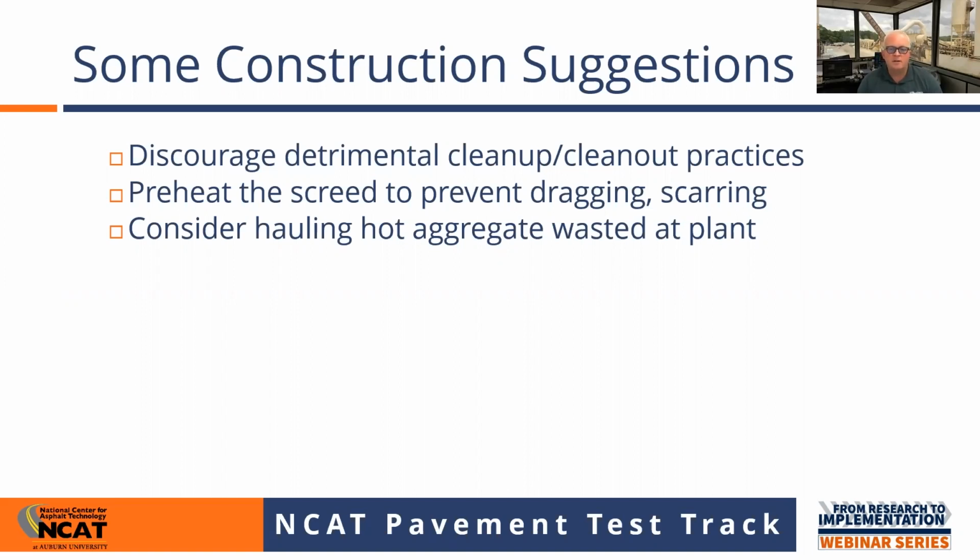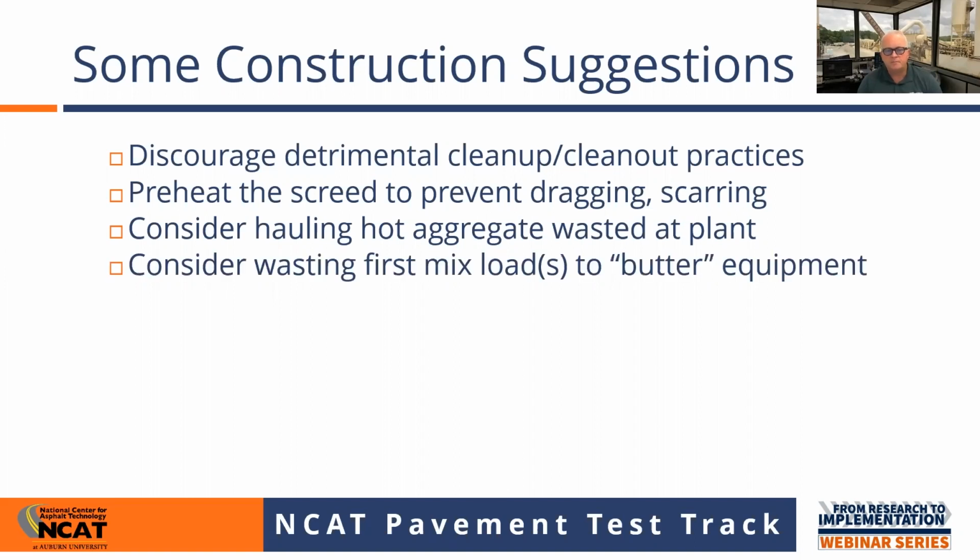And so if you consider hauling hot aggregate that you're wasting at the plant, or using that maybe to preheat your trucks, or maybe even preheat your transfer device, and just discharging that material, that uncoated material, off on the shoulder. But you can also consider wasting your first load of mix at the job site, and you got to be prepared for that. You got to have a specification in place for that, and you got to have payment in place for that. But if you'll run that first load through everything, through the shuttle buggy and through the paver, discharge it on the side of the road, you got to have equipment to pick it back up and haul it off. But you can use that to heat up and to, quote, butter the equipment.